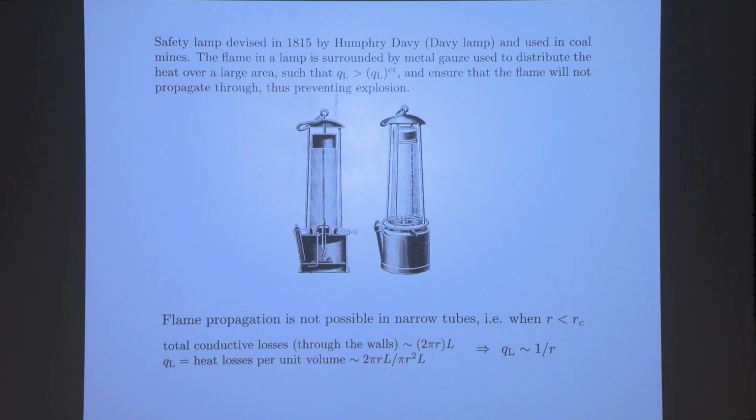You put a torch, you let the flame propagate through the channel, and if it does, great, you reduce the radius until it doesn't, and you say that's the radius. By the way, note that in the discussion earlier, I made a quote-unquote weird assumption that the width is comparable to the flame thickness, which may suggest the flame will never propagate.